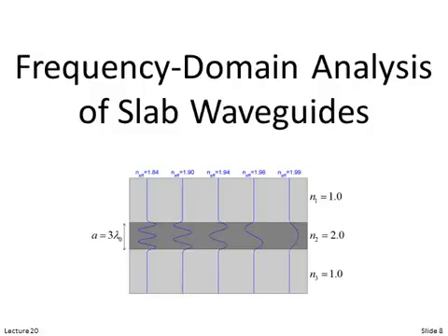So we'll calculate these modes, and then given that, we can excite any combination of those modes that we want into our waveguide. And we also need the same analysis to figure out on the other end how much power ends up in each of those modes. Waveguide discontinuities, whether it's bends or some kind of bump or anything like that, can scramble energy between the different modes, and we might need to distinguish how much power ends up in each of those modes and calculate how much energy goes from one mode into the other, etc.